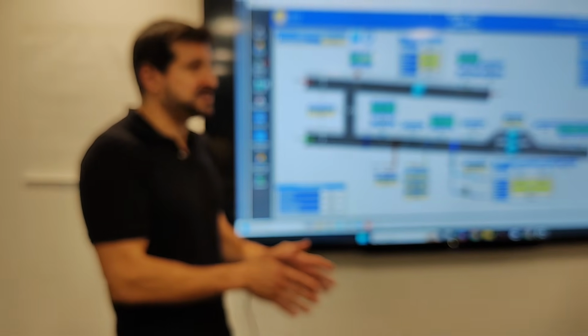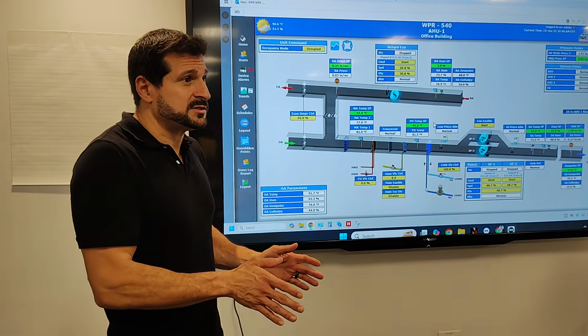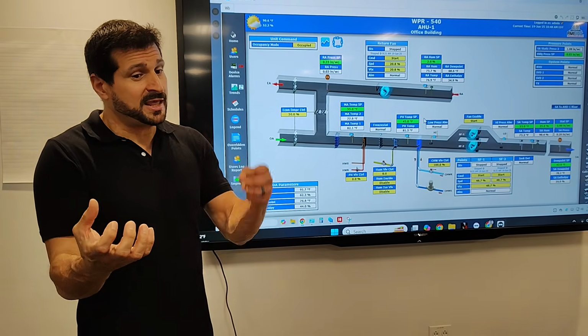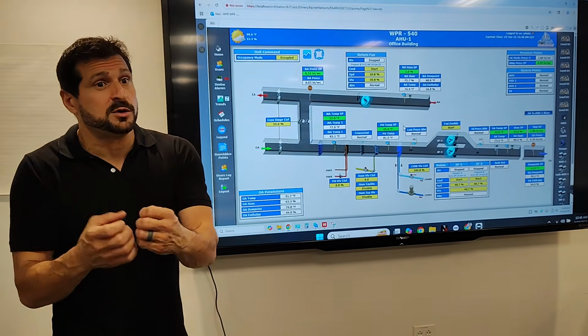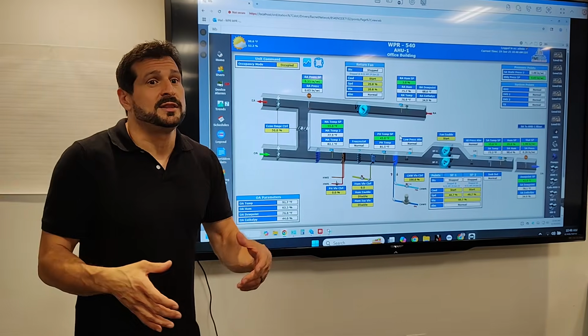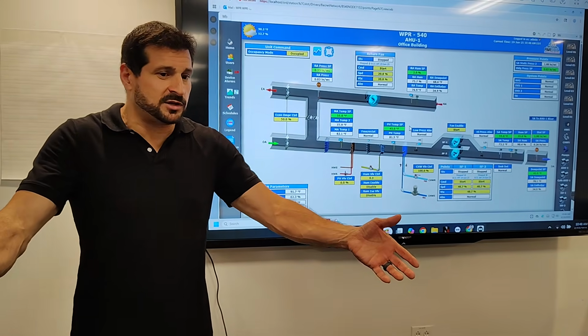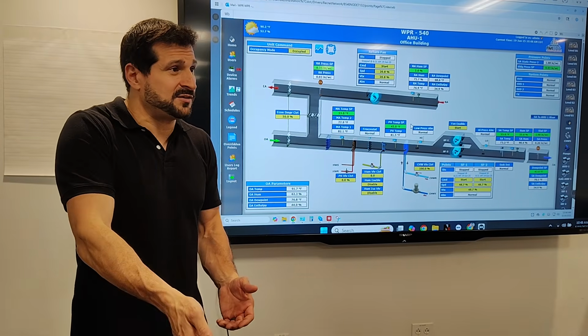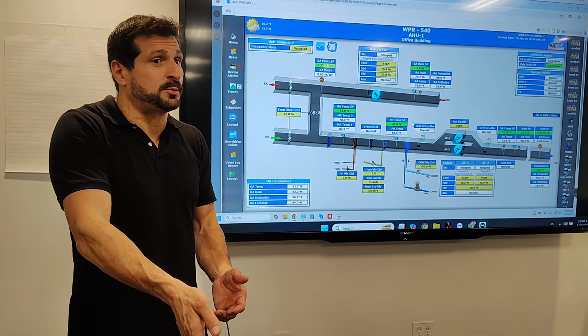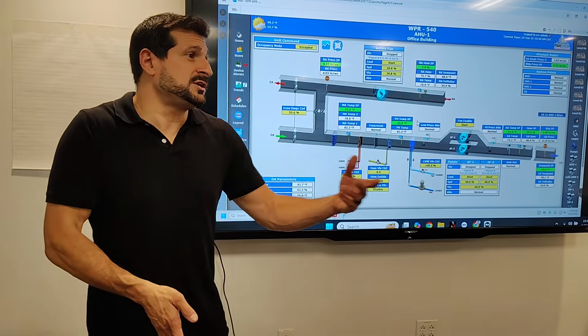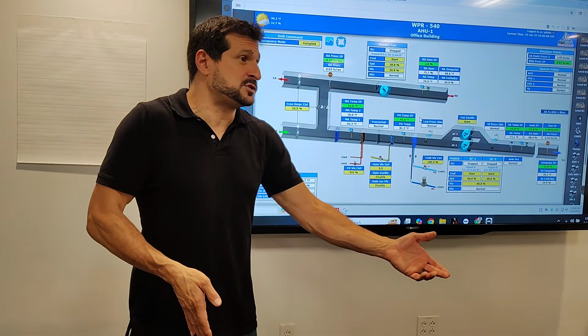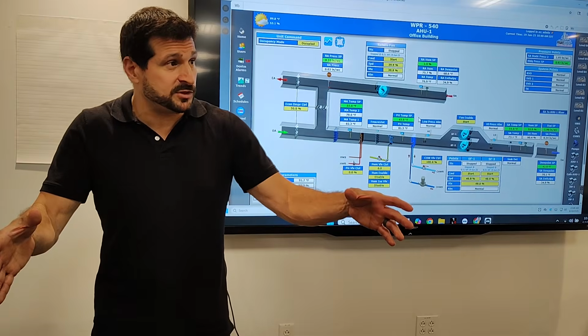Most of these things, the smallest number you ever get to is 25% now. The ventilation index has to do with per person in the space and space square footage based on the occupant design. Let's say this was done as a classroom. This would be 15 CFM of ventilation per person in the room plus 0.6 CFM per square foot of the space. That's the minimum ventilation of this space.